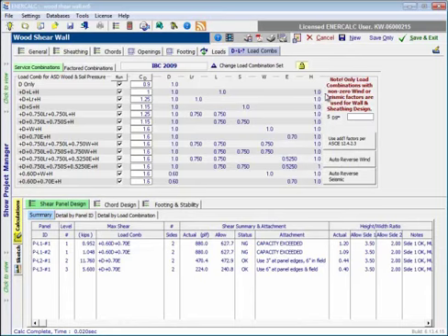On the right hand side we have a note that says what I just described, that only load combinations with non-zero wind or seismic factors are used for wall and sheathing design. Okay, so that just reiterates what I just covered. If we choose to use the additional factor on dead load due to seismic effects, then we can check that box and enter a value so that it knows what to use in that multiplication, and then we would see those additional effects indicated on the dead load portion of our load combinations.